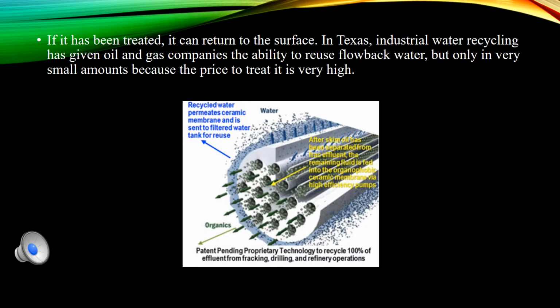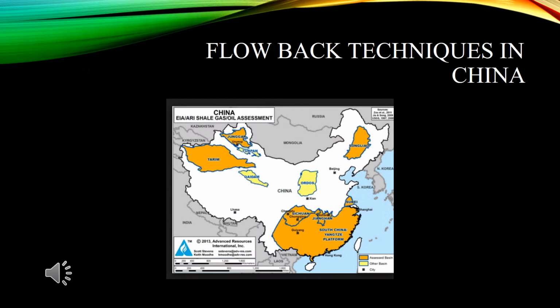In order to reuse the flowback water, it must first be treated. Only water that rises to the surface in the first 10 days is considered practical to reuse and recycle. Not only does the recycling make the use for clean water drop, but it also reduces the need for disposal of the bad water. If water has to be trucked off, it can add up quickly, normally consisting of millions of gallons that either need to be hauled off or inserted into an injection well.